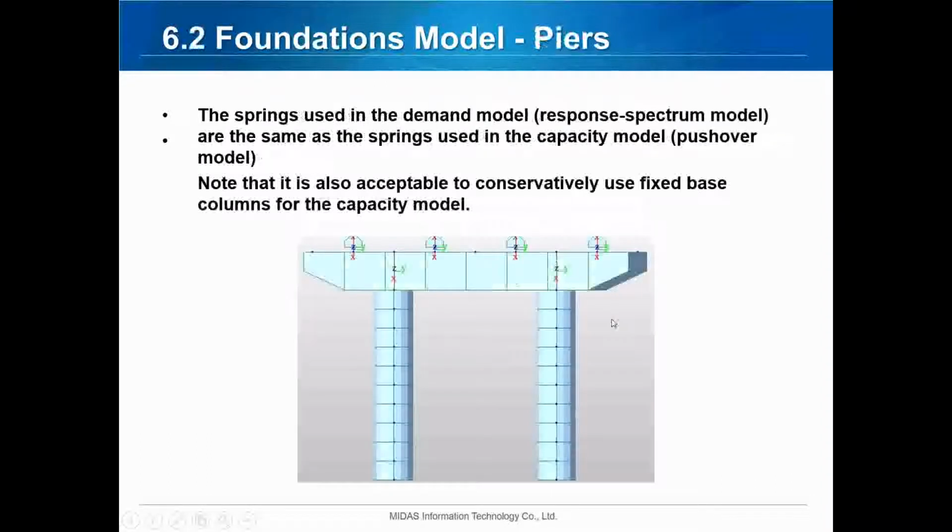And for the PM model, I wanted to mention the springs used in the demand model. We use the same as the springs that we used in our capacity or pushover model. And also wanted to note here that it is conservative to use a fixed base column to do the capacity model, which is what we did for our bridge here.